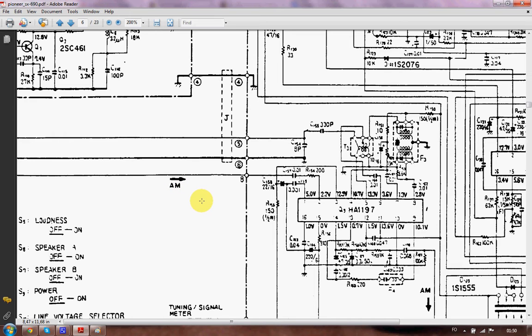And if there's no AM input, the source for that fault is behind. It's somewhere further back, so you don't need to look at this further spot where it enters if the AM signal has disappeared, because the problem is going to be further back if there's no curve shown on the oscilloscope when you try this terminal where it says 2.2 volts where it enters, or that terminal 8 right there, which is the same wire basically.